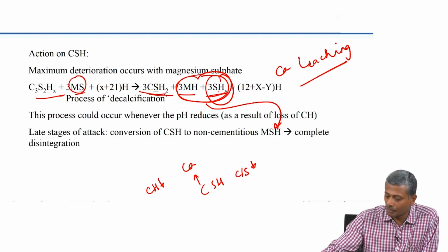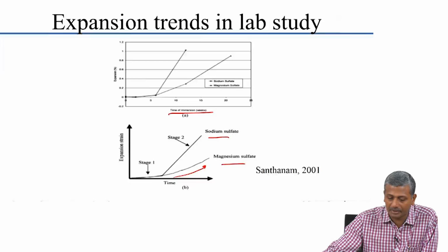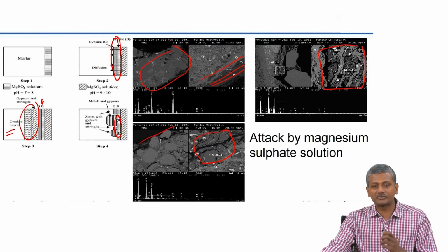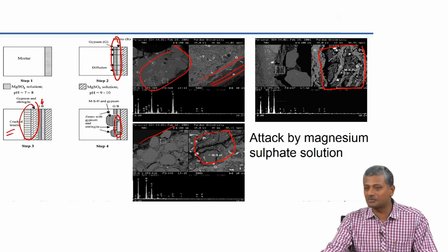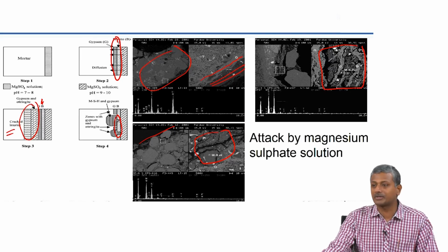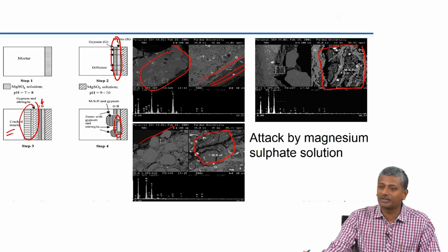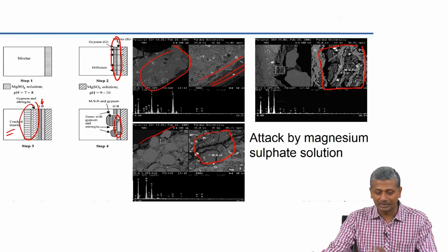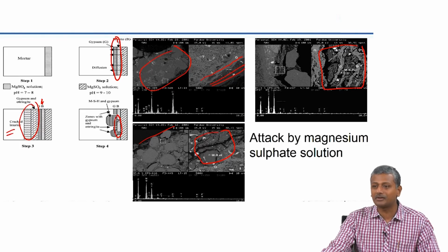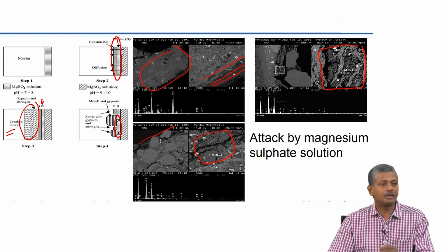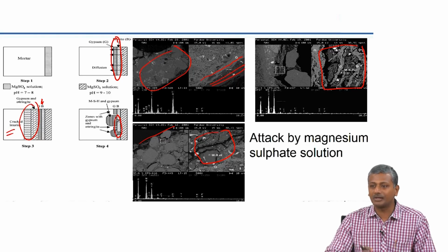So, this is almost forming in bands here, you can see in the microstructural study, and that is what makes microstructural analysis of sulfate attack very interesting, because you get to see these features. If you look at regular concrete under the microstructure, it always looks the same. So, trying to figure out differences between two sets of concrete can be quite difficult and frustrating at times. In sulfate attack or any chemical deterioration, you see a lot of alterations to the structure, increase in porosity, deposition of attack products, which makes it very interesting to do this.